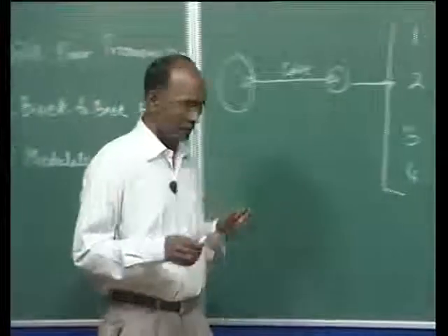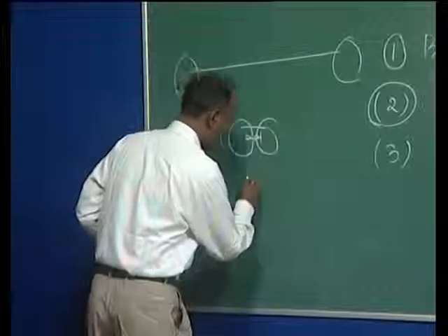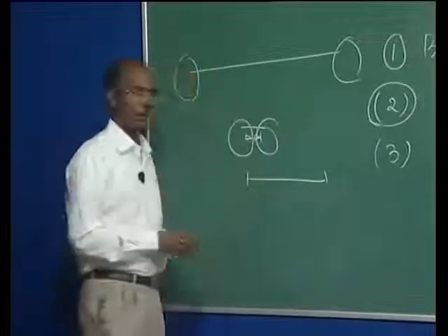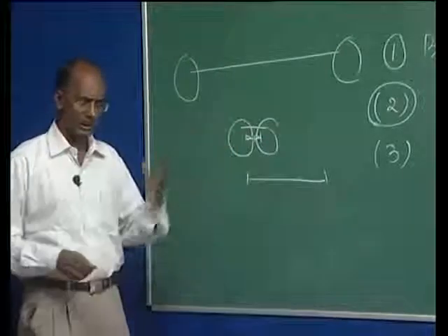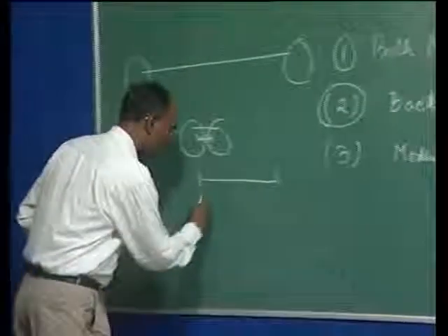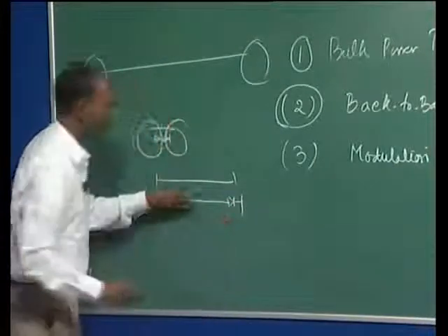Here the modulation of the AC-DC system basically means that if you have an AC line and this line is very weak, sometimes there is some problem due to power oscillations, or power swings, we can have another, small HVDC link that can support this one.